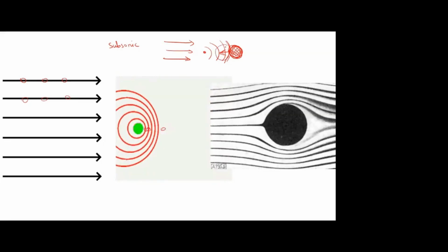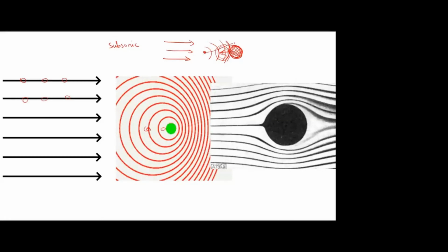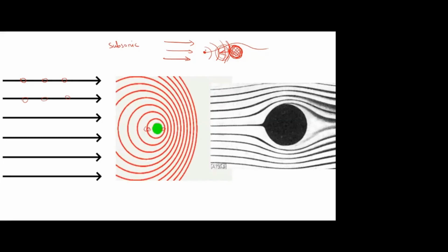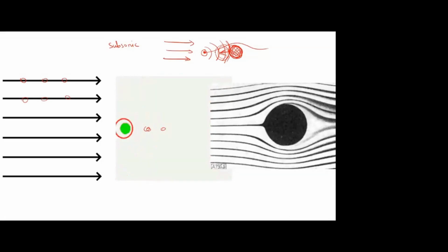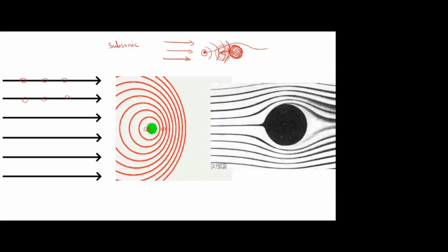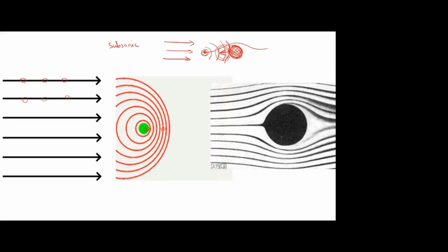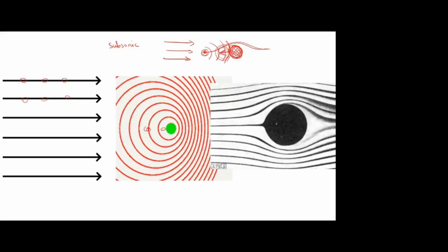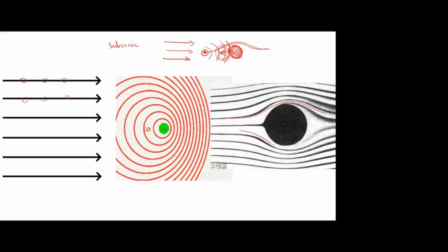So depending upon these disturbed waves, this particle adjusts its path and flows smoothly over the object. In the flow field, the first wave hits the object, and the reflected waves and the upcoming waves both collide and create some disturbance. Depending upon the disturbance, since some object is there, it adjusts its path and flows smoothly over the object. That's why in the subsonic flow, whether it is an airfoil or any object, we will get these smooth lines. Is it clear?